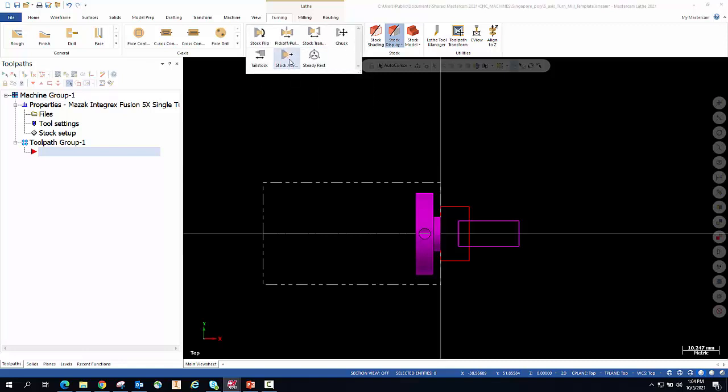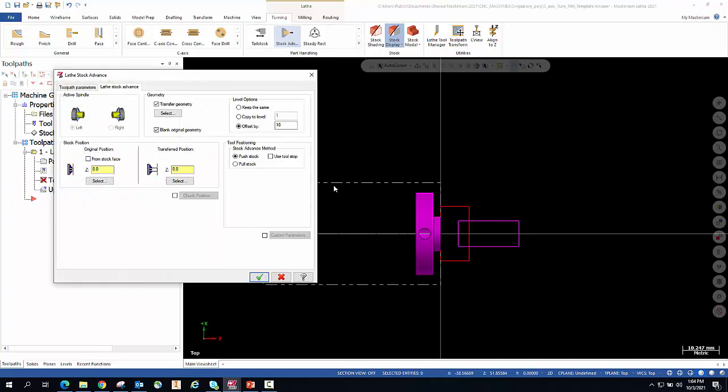We like to do the stock advance, meaning we like to pull out the bar. So to get the stock advance geometry, we are not going to move any of the geometry because it is already positioned correctly. We simply like to move out the bar to 1 mm distance. 1 mm, we have to match over here. This is to simulate the auto bar feeding environment, because on our machine we are having manual movement, but we need to simulate.